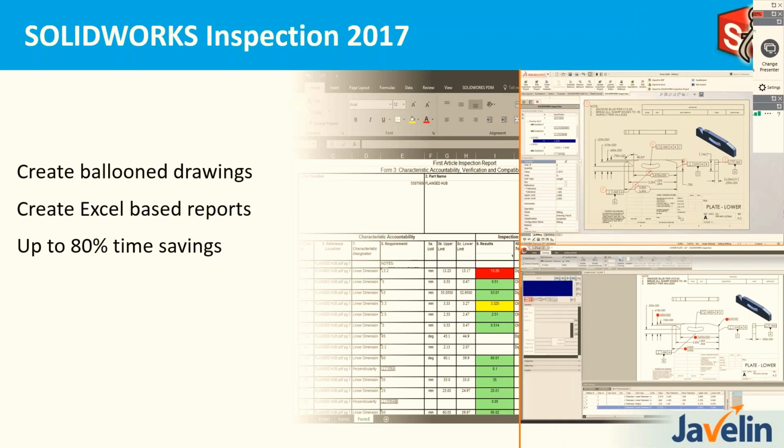With SOLIDWORKS Inspection, you create ballooned drawings, and then we can export that as a PDF. We also create Excel-based reports, which are your first article inspection reports. If we look at before inspection, maybe you're doing it manually. Maybe you're ballooning your drawings by hand. Or when we're talking about reports, maybe you're writing it out manually, or you do have an Excel template, but again, that changes, and then you have to import that manually as well.